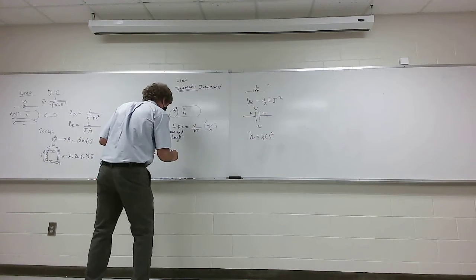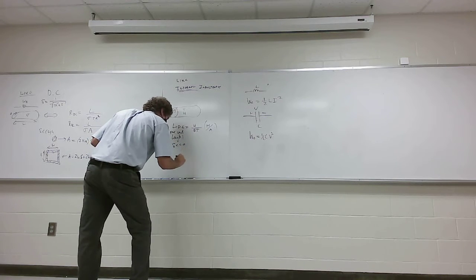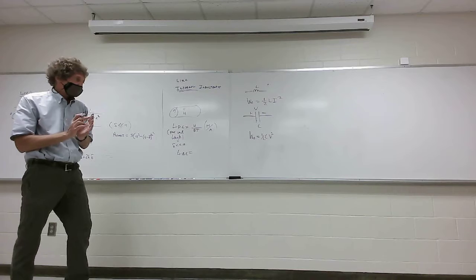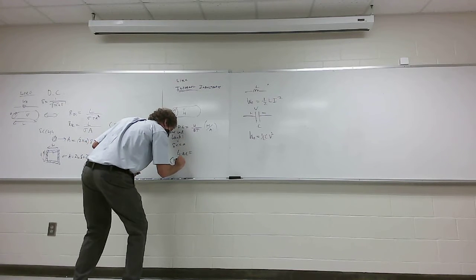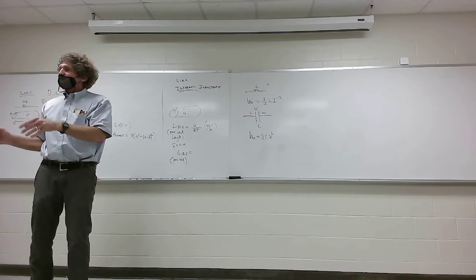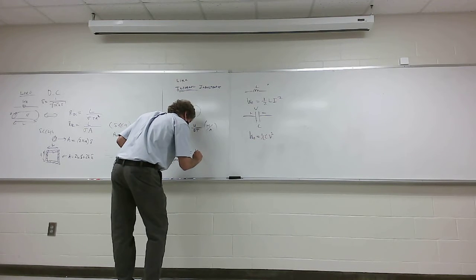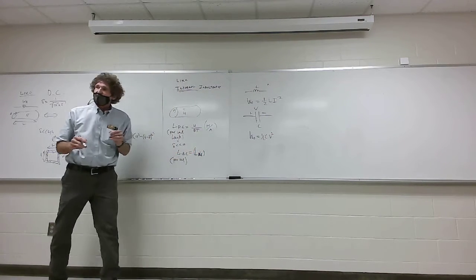Okay, so that's the DC inductance, but it's only internal. Do you remember what I talked about with AC inductance, when all of a sudden the skin depth is much less than A? There's the L, and I call it AC, but it could be high frequency. Sometimes they'll put inductance high frequency, and this will be per unit as well. Anybody remember? What I like to do, Wentworth does it, take the DC per meter. So just put L DC.